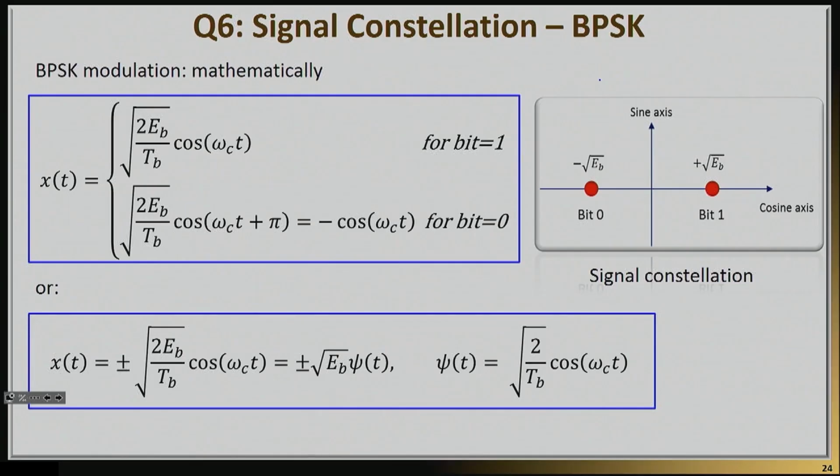The whole idea behind visualizing a modulation scheme comes from the fact that we're only using sines and cosines. These are, again, orthogonal signals. In binary phase shift keying, for example, which is almost the same as an ASK with two different amplitudes, you can encode the signal in the phase. You can have either a phase of 0 or a phase of pi. Essentially, you end up with either a number times a cosine or minus that number times a cosine.